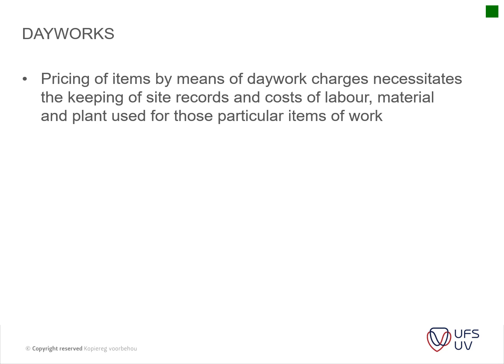bricklayer, or a tariff for a certain type of artisan, or just a general labor on site, and now you have an addition to the project, and now you can refer back to those labor rates and say, okay, this item will take me 2 days longer. It will include this artisan and this laborer to do this work. It will take him 2 days. This is the rate per hour, and then you can calculate what the total cost for that item would be.